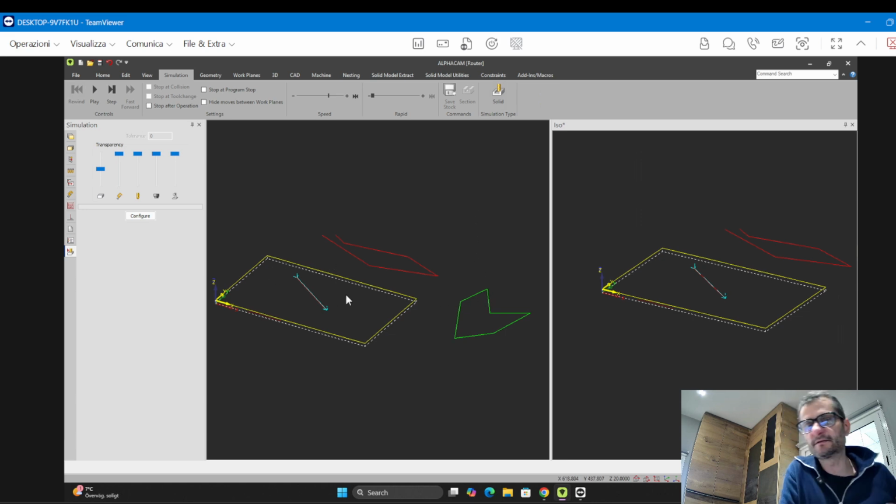This one is called wireframe, or not solid. It gives us some information, because you can see the tool working, but you don't know a lot of things, like if the tool is flat or if the tool has some shapes, because it's not solid. Or you can switch on the solid.